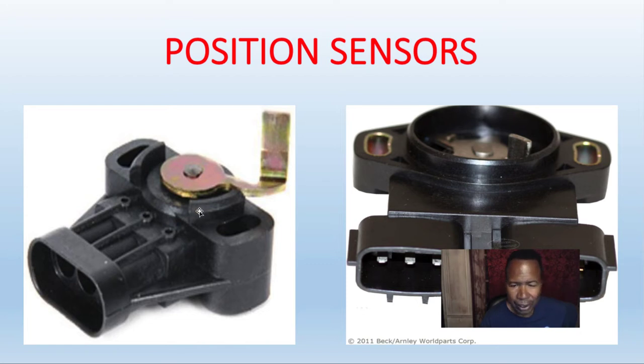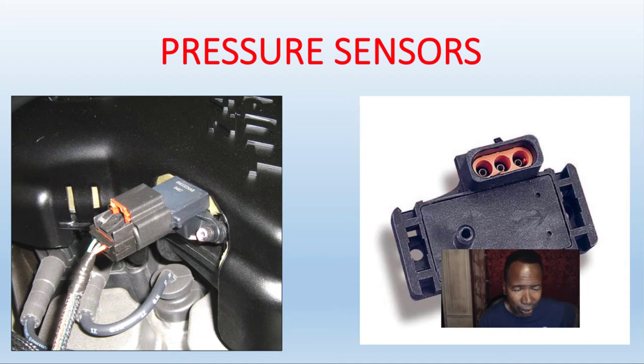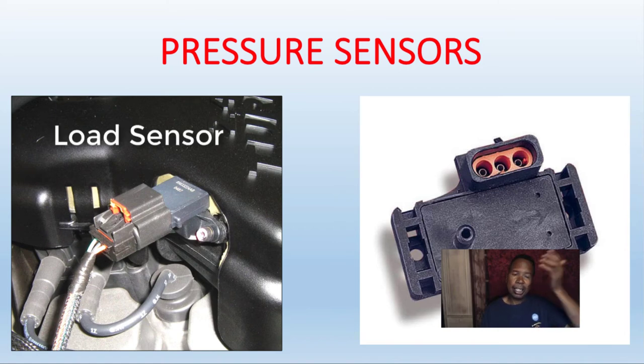The throttle position sensor is the driver demand sensor that tells the computer where the throttle is located. The plate. Is it closed, halfway open, wide open? Now, besides a TPS signal, an analog DC voltage can be a M.A.P sensor, which is here.